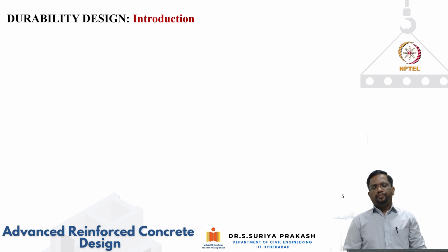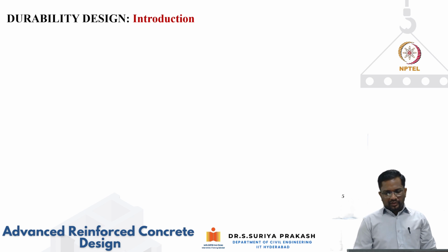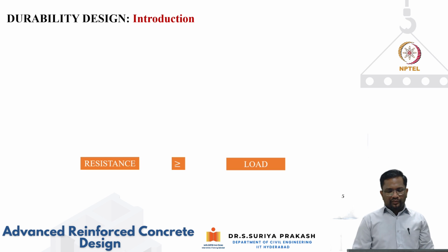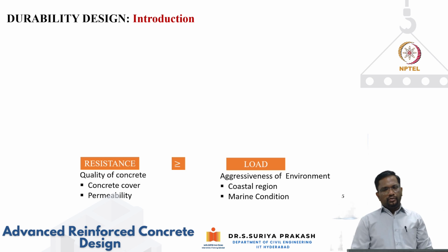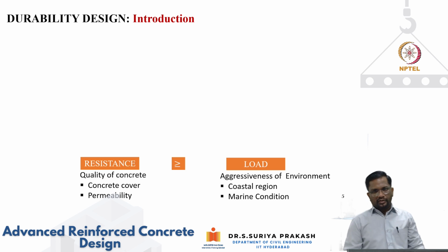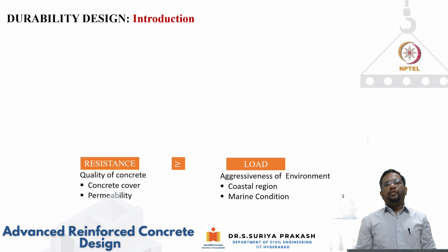We have seen this in the very first part of this module. Resistance to corrosion mainly depends upon how good the impermeability of the concrete is, and also how good the quality of cover is, because that is basically the gate which allows the entry of deleterious substances.